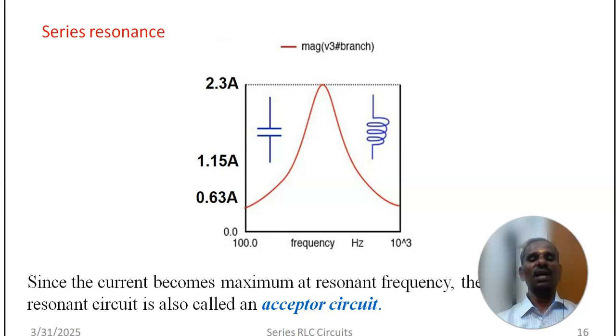So this is the analysis that we have made. Before, it was 50 millihenry and theta was minus 55 degrees, whereas when your inductance value increases to 506.7 millihenry, the theta value is 0, which is in phase with your current. So it is a purely resistive network.